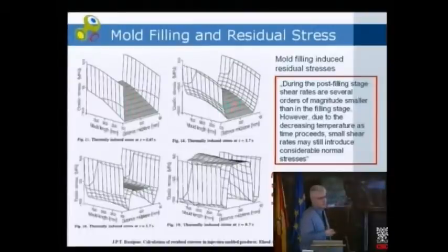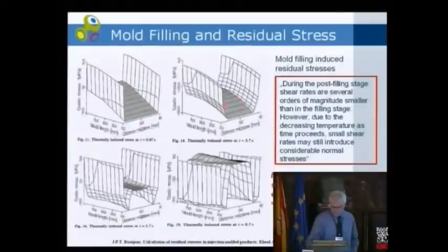So Paul mentioned this morning, there are often people coming and saying they have debinding problems. This is one of the debinding problems, because if you debind such a component, it becomes very unstable. And if you have these high stresses, then you will produce cracks below the surface, and you have cracking of components. And this evolution of stresses is even worse during the packing phase. This is the holding time when you have filled the mold.